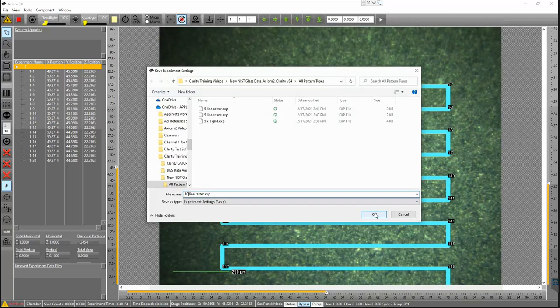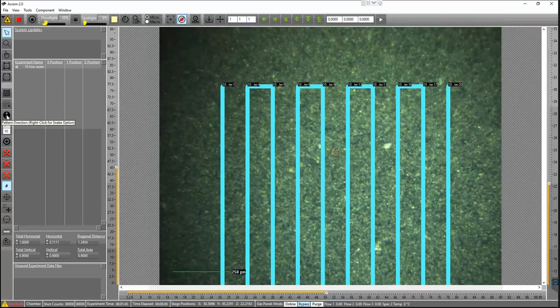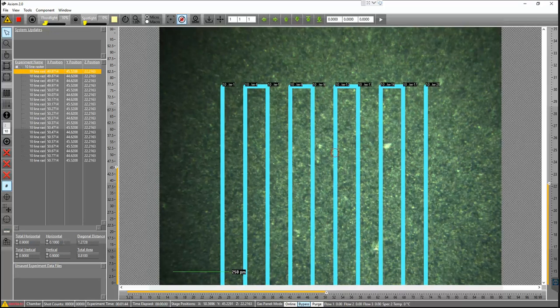One other thing that I'd like to point out is I can change the directionality. If I change the directionality, now I have roughly the same spacing in the horizontal orientation. I'm going to get rid of these ones. I'm just going to make it straight up 0.1. So I'll delete those and hit enter, and I'll make the total vertical 1. So now this is the same raster, only it's oriented in the vertical orientation.